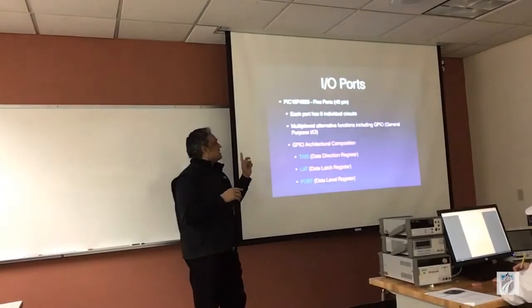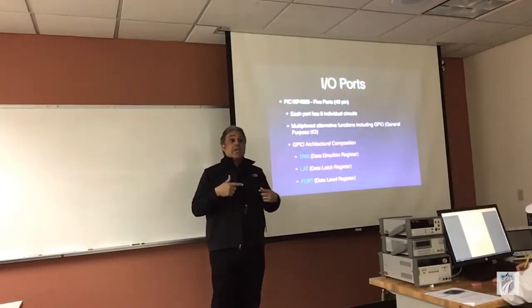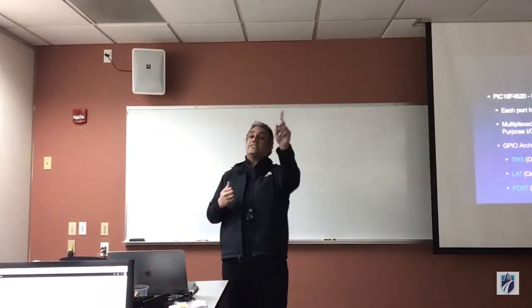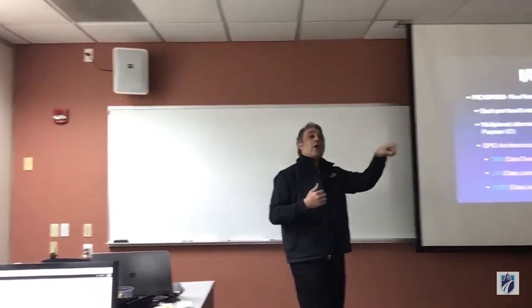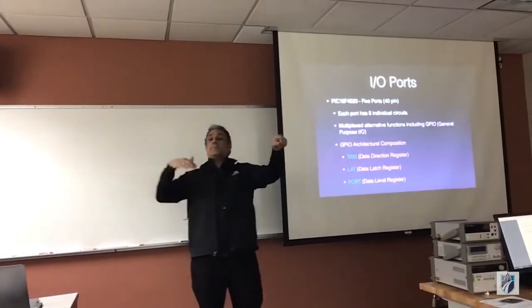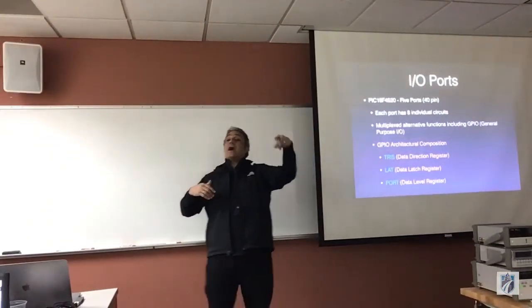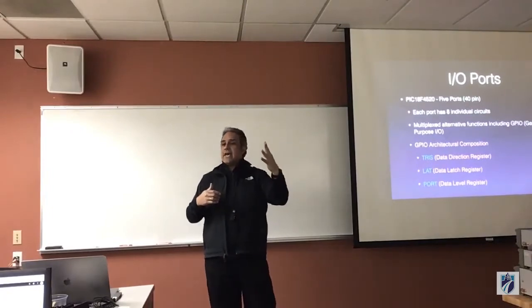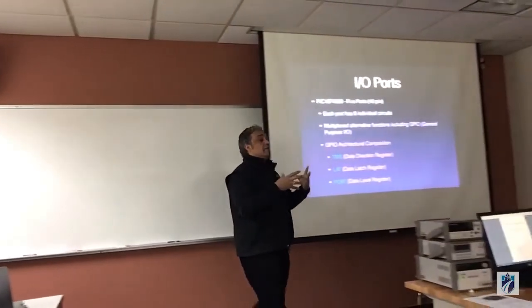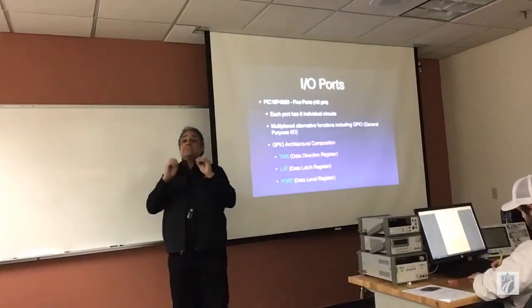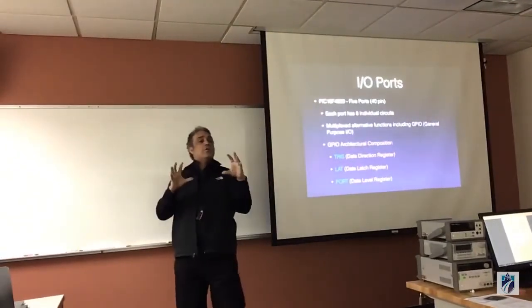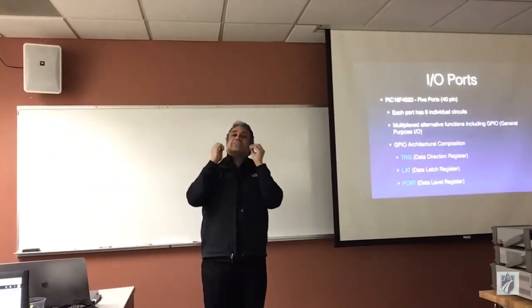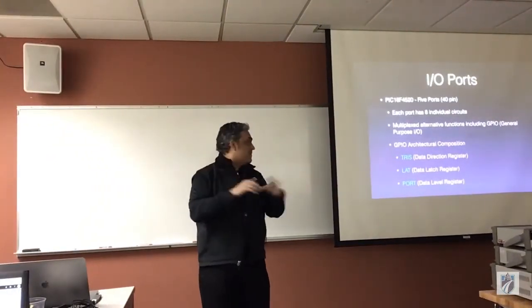The second part is that every single one of these pins is going to have a multiplex function in it. That means that that circuit could operate as an input-output pin, right? A general purpose input-output, but it could also have alternative behaviors to it. And so what we're going to do today is learn how to handle the general purpose digital input-output. So we're only going to be talking about the input-output behavior of these circuits in its digital form, okay? That's the idea behind it.